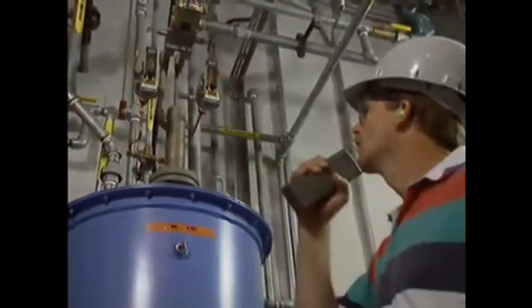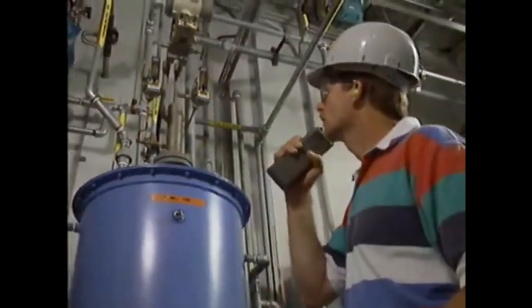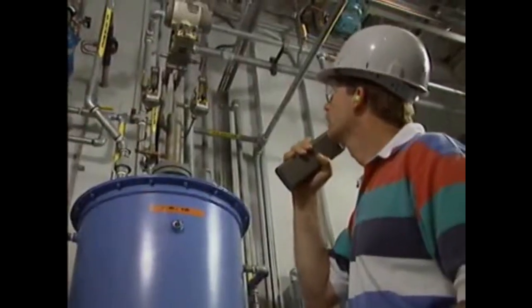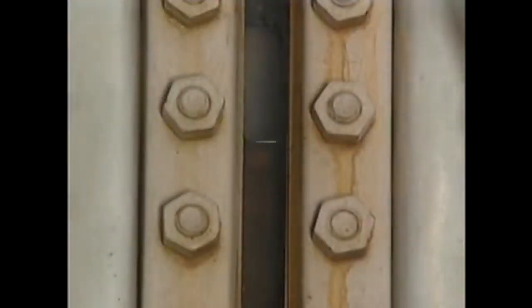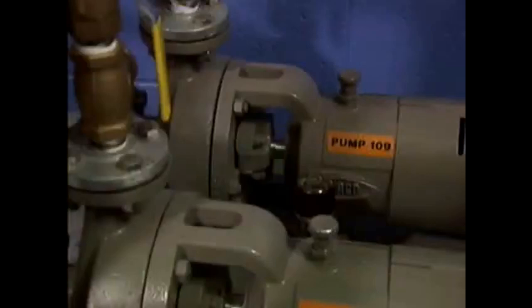The level indication system appears to be operating properly. After checking the rest of the local indicators at the feed tank and finding nothing wrong, the operators rule out the feed tank as a possible cause of the problem. When the outside operator checks the collecting tank, he finds nothing wrong. The local level indication matches the indication in the control room, so the cause of the problem does not appear to be the collecting tank. The operators now check the transfer pump and its associated controls.